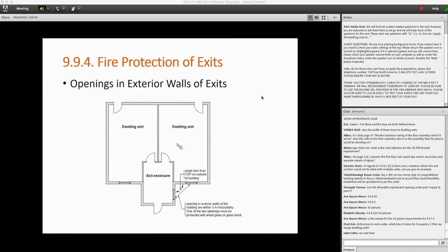Now, in addition to that, the lobby is required to be fire separated from the adjacent occupancies that are permitted to open onto the lobby. In a sprinkled floor area, that fire separation need not have a fire resistance rating. But if you have a non-sprinkled area, the adjacent occupancy has to be fire separated from the lobby by a fire separation with a fire resistance rating, which is typically 45 minutes for a building that is built to Part 9. And passenger elevators are also permitted to open onto the lobby.